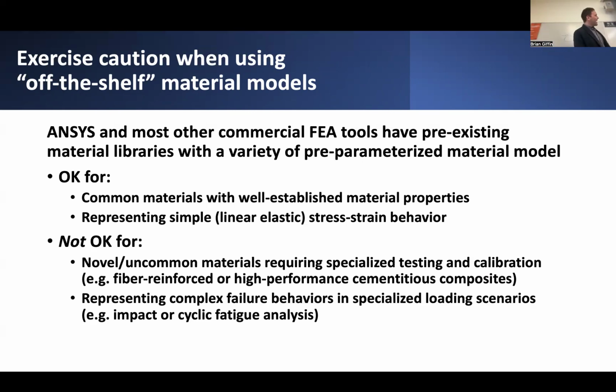So in general, I would say if you are trying to just stick within this linear elastic regime, or even within a reasonable nonlinear elastoplastic regime, these pre-calibrated models are probably okay to use. And they're certainly a great starting point if you just want to get something working, test out your finite element analysis, and have something to baseline your analysis against.